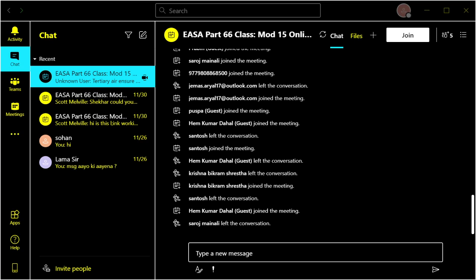So the oil jets are also calibrated to the pump output. You'll have a pressure bypass as normal. You'll have pressure limiting valves, cold starting blockage components, and essentially, which you want to remember here, is a pressure differential switch, which will give you a flight deck indication. We'll show you that in a minute. So looking at the full flow system, not much difference, is there? It looks very, very similar.